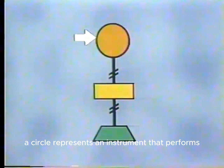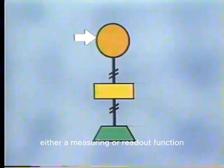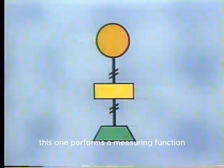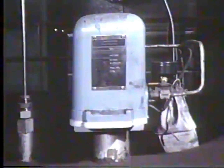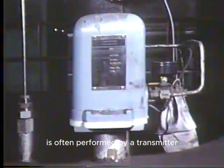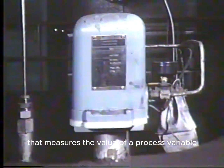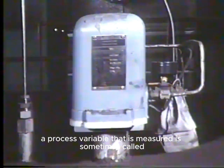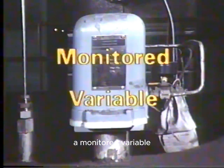A circle represents an instrument that performs either a measuring or readout function. This one performs a measuring function. The measuring function for pneumatic control systems is often performed by a transmitter that measures the value of a process variable and produces an output signal that represents this value. A process variable that is measured is sometimes called a monitored variable.